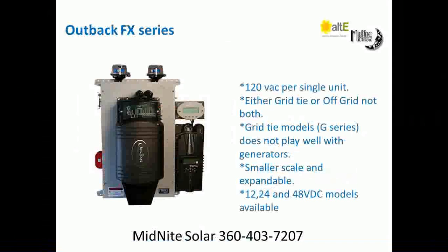Like I say, if you need a small 120 volt only grid tie system, this is a very affordable, very capable grid tie inverter, but it does not support generator. One of the other benefits of it is it does come in 12, 24, and 48 volt models. I do want to point out as well that the FX series does support generators very well. The GFX or GVFX does not support generators very well.